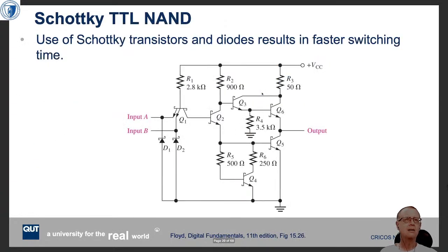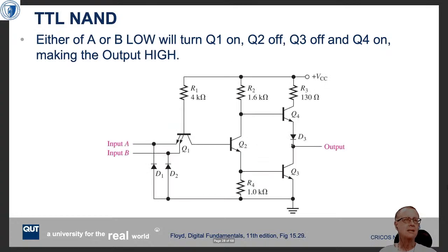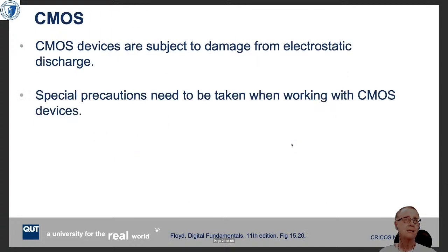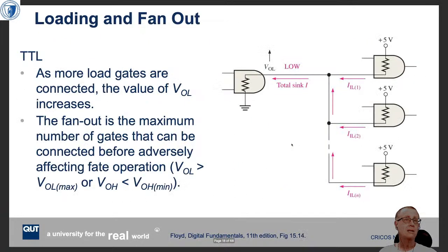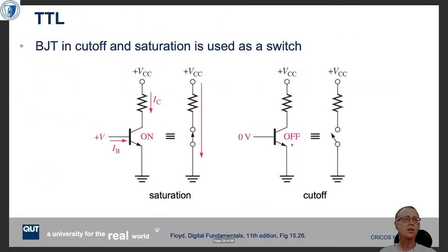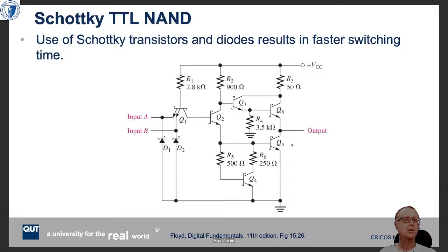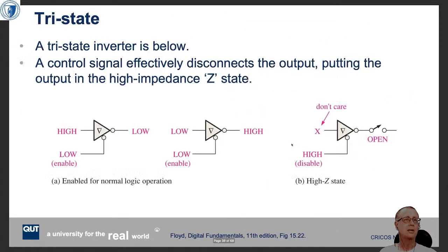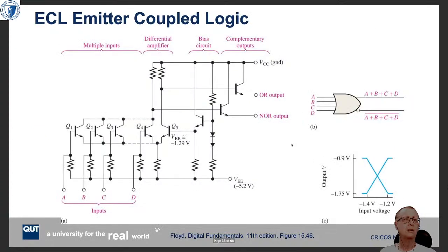If we go back here, right? Here we've got a push-pull pair as the output for this example, and let's go here, so same thing, push-pull pairs. Right, but the difference with emitter coupled logic is the emitter goes straight out. Yeah, the emitter goes straight out.